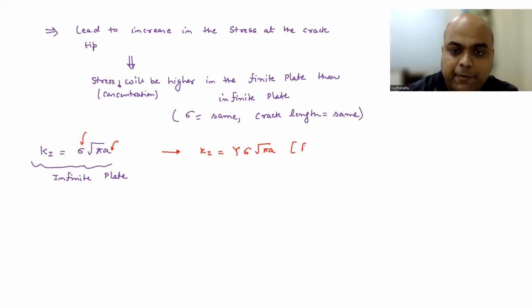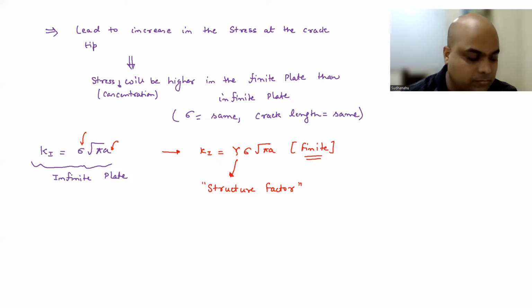So for a finite plate, we can write the stress intensity factor as Y sigma root pi a, where Y is called the structure factor, and its value will be greater than or equal to 1.